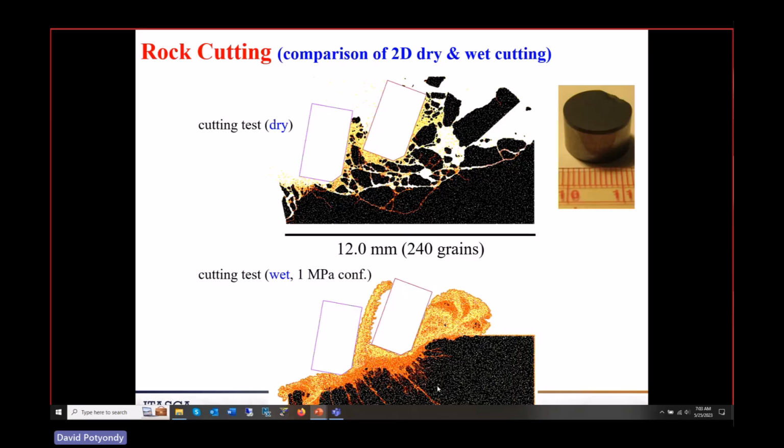You also see in here that the cutters are never in contact with the virgin rock. They're always in contact with broken bits of rock that are then pushing against this. This is what they believe really happens in cutters, and this is why they believe that tiny changes to the geometry of the chamfer have giant effects on energy to cut.